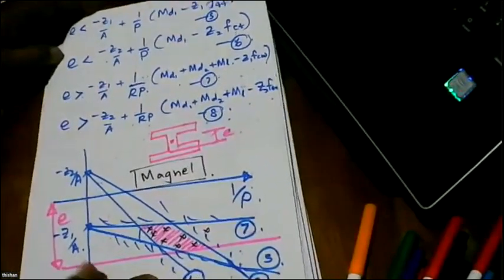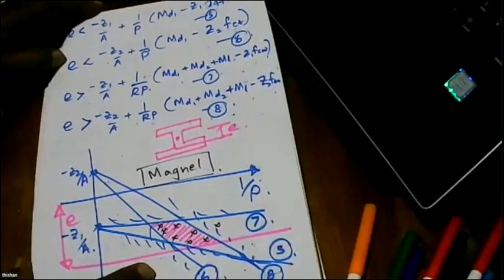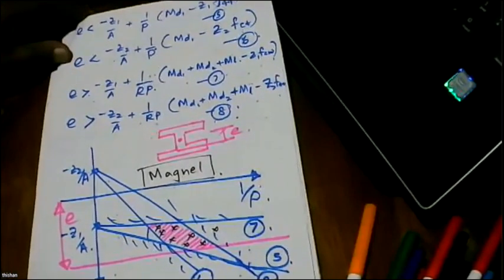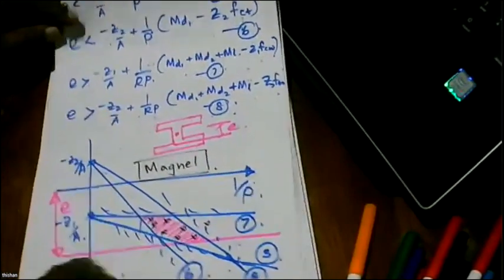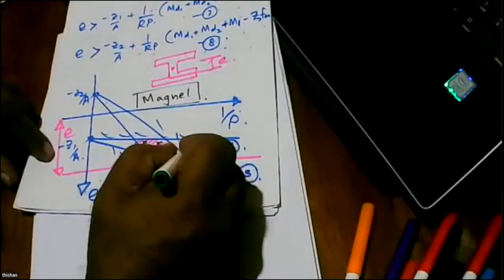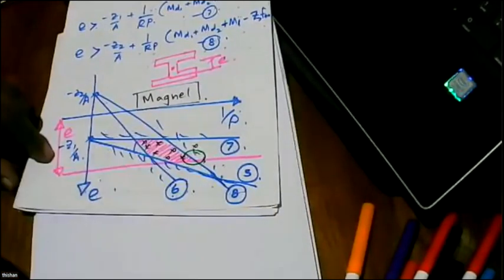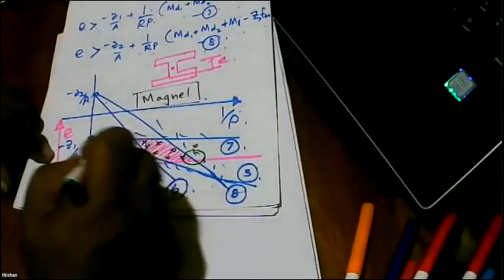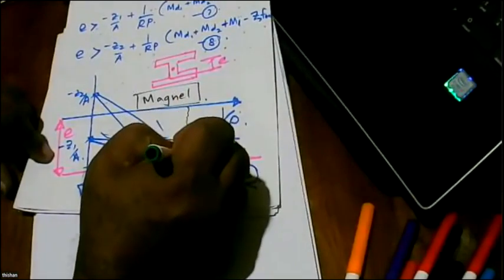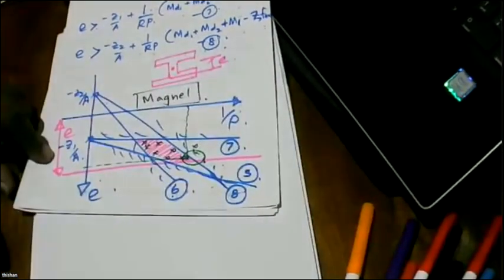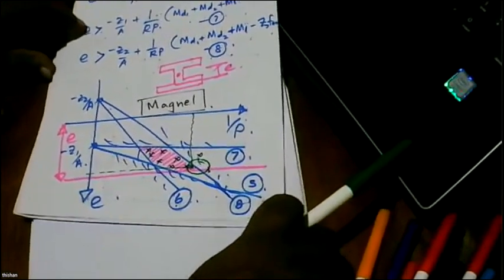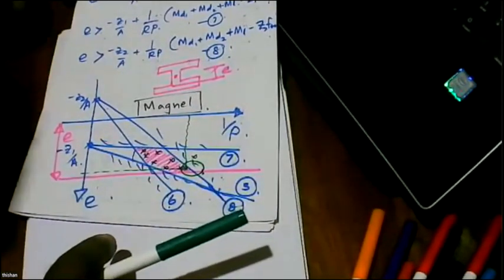Last time we introduced the fundamentals of prestressed concrete, and we derived these equations. Then at last, I told you that if you can select a section, that means eccentricity is somewhere there, prestress is somewhere there, then we can go for a minimum prestress. Then you'll ask why minimum prestress? Because steel is very expensive, so we must go for minimum prestress.